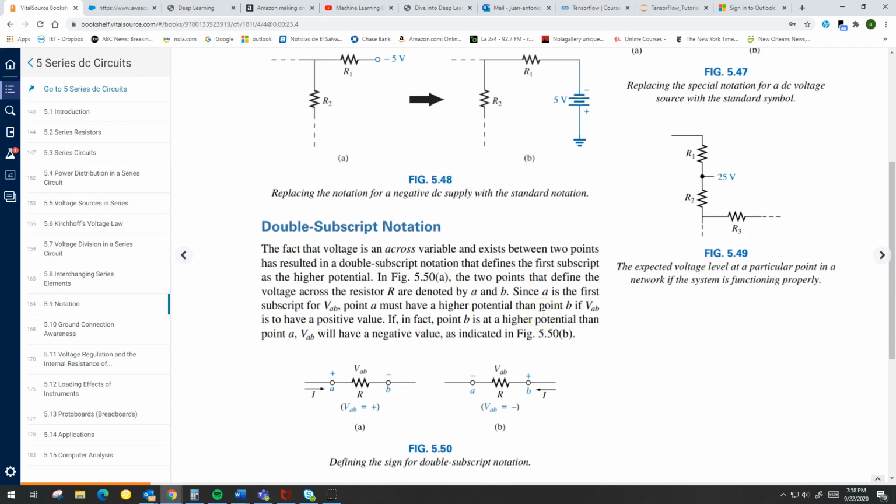All right. This is also another good example. It's telling me here that between R1 and R2, there's a source being connected. See, there's a source connected to a 25-volt source. So how do I know that? I know then this point will be connected to the positive of this battery, and the other side of the battery will go to ground. See, it's just a notation.